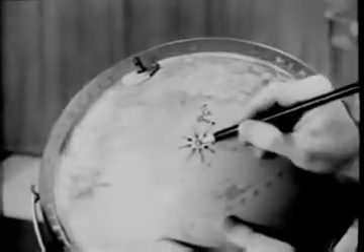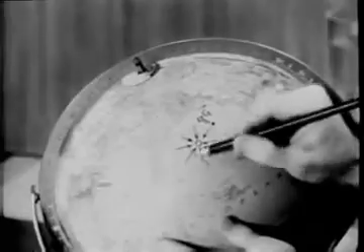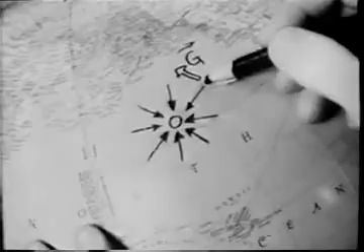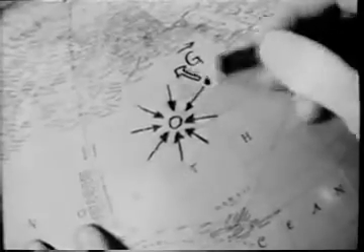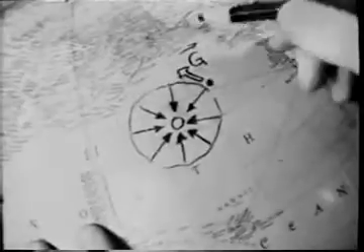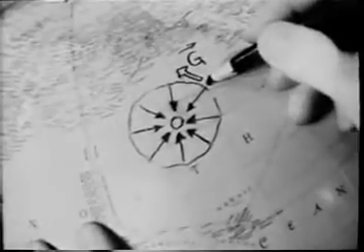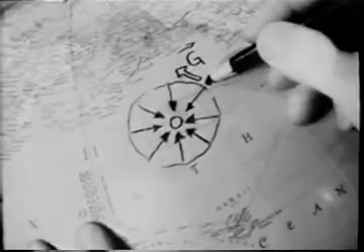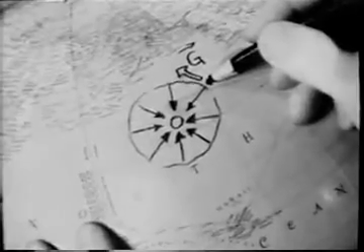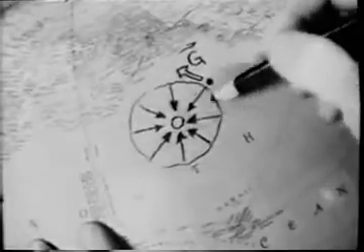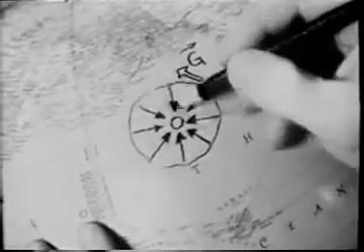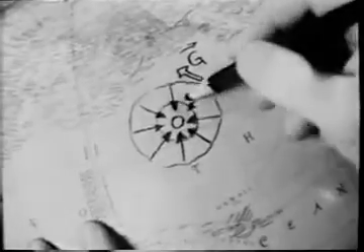Let's imagine that this is the drain. The water flows radially inward from all directions. The Coriolis force acting on a fluid particle in the northern hemisphere as it moves radially inward is circumferential and counterclockwise. This force, integrated around a circle, contributes a counterclockwise torque in Kelvin's theorem. This tends to make the circulation increase with time counterclockwise. In the reference frame of the Earth, a fluid circle, which starts at one radius with zero circulation, acquires, or should acquire, counterclockwise circulation as time proceeds.